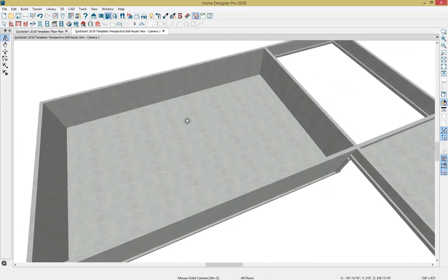So this is a good example of how you can create a plan with different foundation options in Home Designer software. In this plan in particular, we have an unfinished basement, a crawl space, and then a slab foundation. Next, let's go ahead and connect our unfinished basement to our first floor by adding a U-shaped stair in this corner over here. So to do this, let's work in both 2D and 3D at the same time.